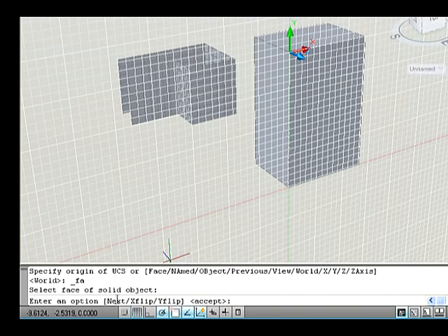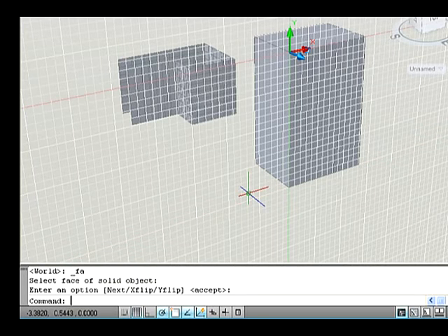Next. It allows you to select another face related to the selected face and places the UCS icon in different vertex points. X-flip. It flips the direction of X-axis. Y-flip. It flips the direction of Y-axis. Now press Enter to complete the selection of UCS.